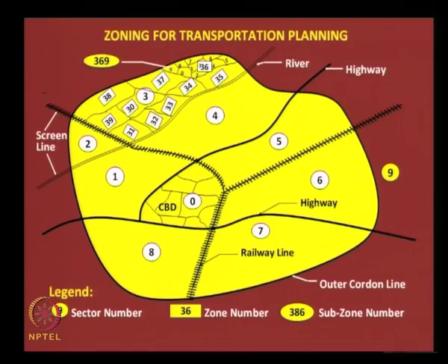They should pass through fixed locations, either level crossing or underpass or overpass. Similarly, if there is a river, there will be bridges providing openings for the traffic to cross at fixed intervals, like openings on a screen, right. So that is how these barriers, where there are fixed locations for traffic to pass through, are termed as screen lines.